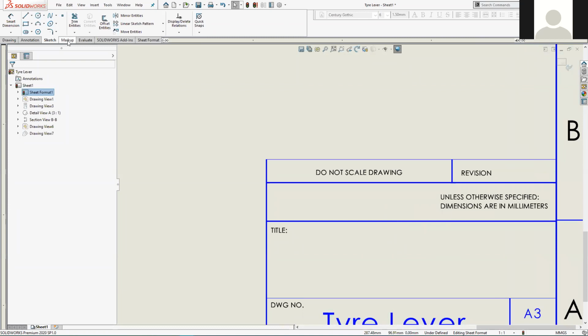So again, we're just in sketching mode. We know how to draw circles in sketching mode. We know how to use the line tool to create straight lines. If you remember, I'm sure we covered that you can turn your sketch geometry between solid lines and what's known as construction geometry, which is essentially a dashed line. So with those tools, we should be able to create this third angle projection symbol. And I think probably the most logical place to start is the circle.